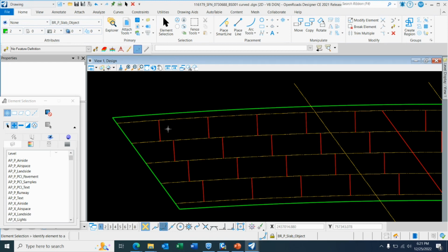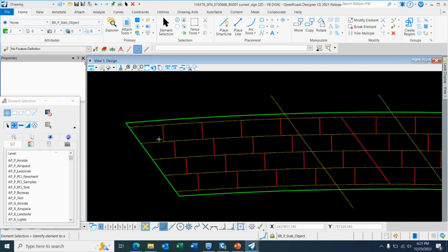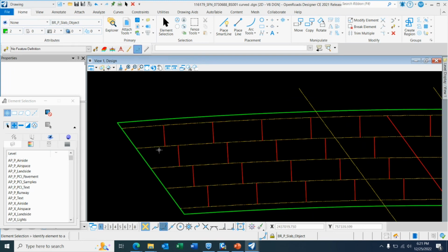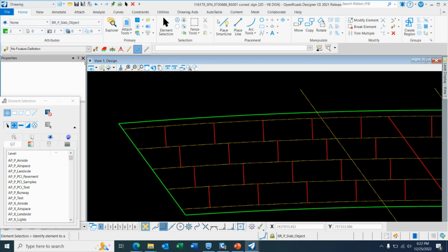So as I said, I will create elements between the intersection points between these structural components. This will ensure that I have a node at the intersection point between diaphragm and beams. The other thing to keep in mind is that since these beams and deck edges are curved, we cannot use curved beam elements. These elements should be replaced by straight lines. If you use curved elements, the Midas software will make them straight and you may not have a correct structural model. So we need to draw these elements using a straight line element.